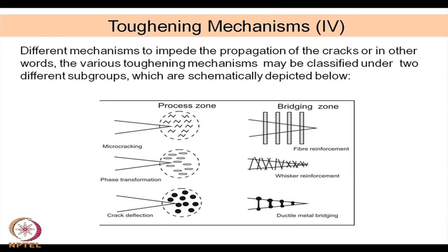you know it is not only the monolithic ceramics, but ceramic matrix composites are also quite important, and there has been extensive development so far as ceramic matrix composites are concerned. One can use different kinds of fibers, even ceramic fibers can be used, silicon carbide fibers or silicon carbide whiskers can be used, even alumina fibers can be used as a reinforcement within another ceramic matrix.